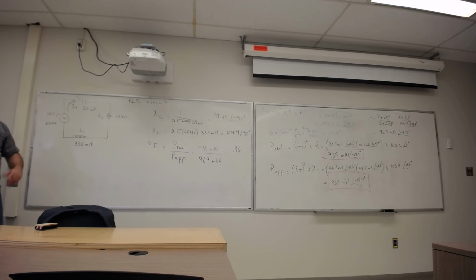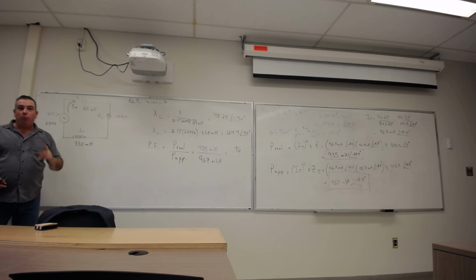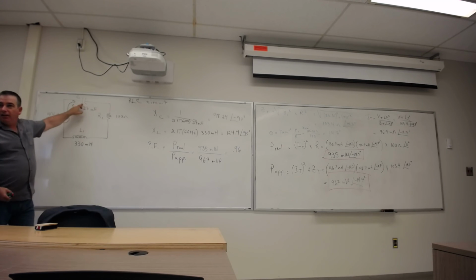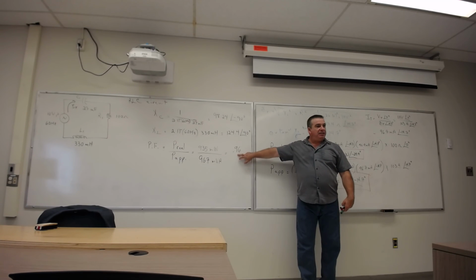So what we do to counter that is, when the power comes into the building and we know that there's inductance in there, we put some capacitance in the system. We actually purposely switch in some capacitors on the line to react against the inductance. Remember, like our little vector diagram, one was pointing one way, so we put in a capacitor that points the opposite way to cancel it out. By putting a capacitor in our circuit, you'll notice that this time, compared to the 2 previous problems, our power factors look, ooh, look how nice it got because of that capacitor.